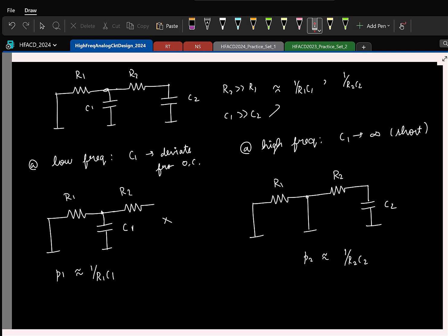Right. So again, you can work out the transfer function and see it across frequencies, and it will be contributed by both the resistance and the impedance. The impedance we have to calculate across frequencies. Correct. But the point is, the assumption is this is going to contribute to the low frequency pole. Till that frequency, looking in is really large. I mean, this can be a small impedance. Doesn't matter, right? If R2 is really large, that is going to dominate. And at low frequencies, the input resistance is large. Impedance is also the same, the series combination of these two, which is very high at low frequency. At high frequencies, it is simply R2.